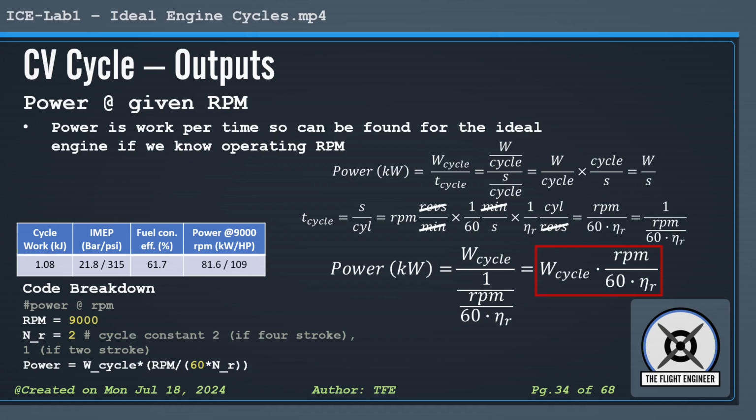With all of our performance estimates shown, let's take a minute and think about what this really means. We have a single-cylinder 500cc engine. It's allegedly operating at almost 62% efficiency. Anyone familiar with engines will tell you that they're only about 30% efficient, so this number's already way off. We also have the same engine producing almost 110 horsepower at 9,000 RPM. Again, this is a ridiculous number. Most engines 4 times this size struggle to produce that power continuously. So our simulation is horrendously inaccurate, but that's okay.